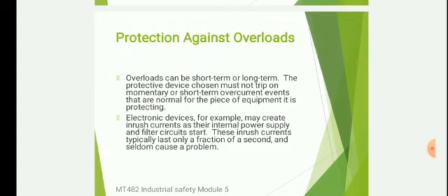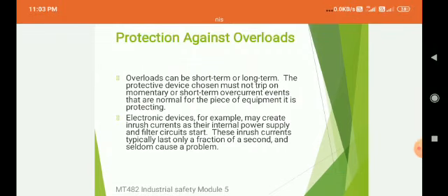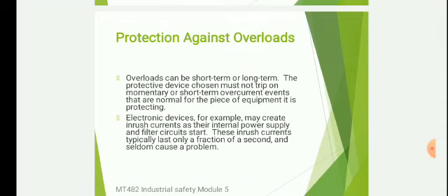Overloads can be short term or long term. It may continue for a long time, or it will disappear after some time. The protective device chosen must not trip on momentary or short term current events that are normal for the piece of equipment it protects. Momentarily, the protective equipment, the circuit breaker, should not trip.